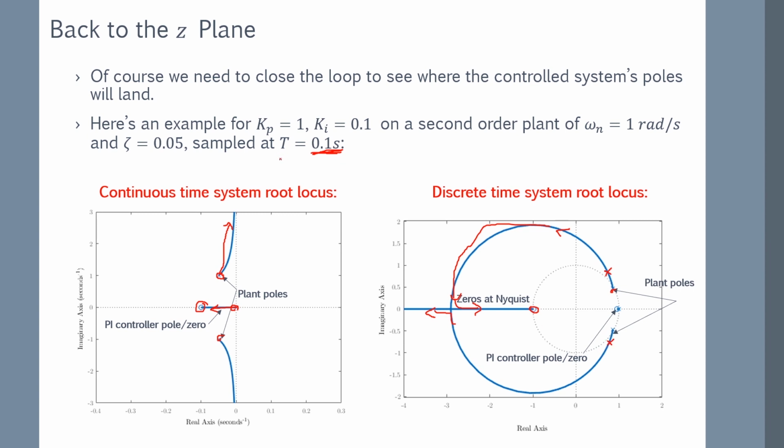And that's, of course, just because the sampling period is too slow for the reaction of the plant. Because if you look back in the continuous domain, you can see that as you increase the gain, your system responds with a higher and higher frequency, which means that now your controller has to have more bandwidth to keep on controlling it. That's a more loose interpretation of how this works. And if your controller doesn't have that bandwidth because it's sampling discretely, then your system becomes unstable. That would be, I think, my take on it.